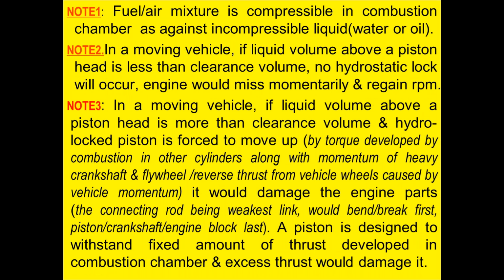Please note certain points here. The fuel air mixture is compressible in the combustion chamber, as against incompressible liquid, that is water or oil. Second thing to be noted, in a moving vehicle, if liquid volume above a piston head is less than clearance volume, no hydrostatic lock will occur. The engine would miss momentarily and regain RPM.